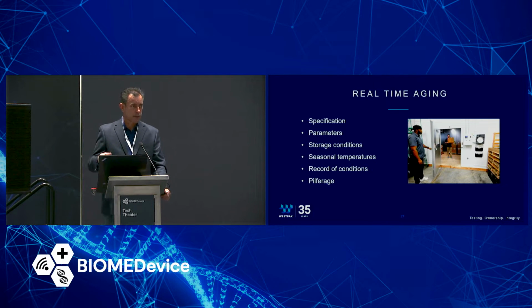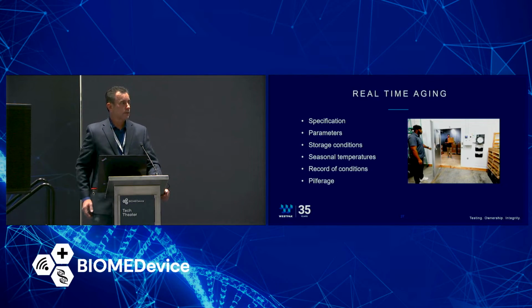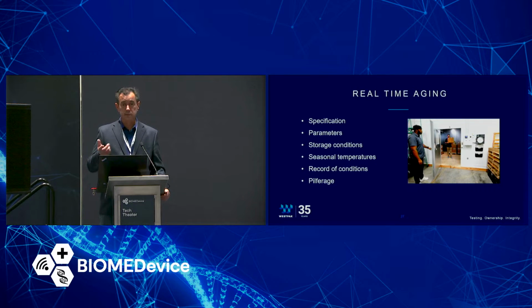So now let's talk about real-time aging. Does anybody know of a real-time aging standard, just by a show of hands? No, because there isn't a standard. There isn't a specification for real-time aging. So how are we going to define the parameters? Storage conditions? Well, as it turns out, we can look to ASTM D4332 and look at standard conditions, but they don't really call them storage conditions. And everybody's storage condition is going to be a little bit different depending on where you are.